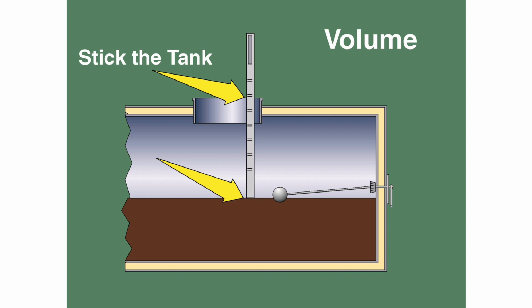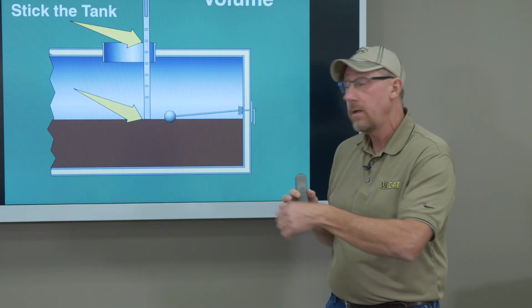It is certified to be for that tank on that truck. So you can take your oil, put your stick in so it just touches the top of the oil, take your reading up here. An Etnyre stick is reverse calibrated, so that will tell you on that line how much material I have in my truck. Then I go spray it, okay?